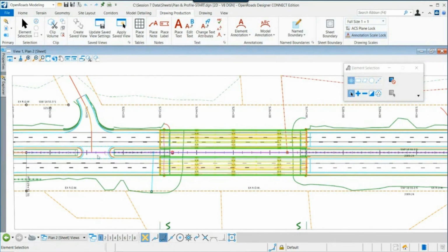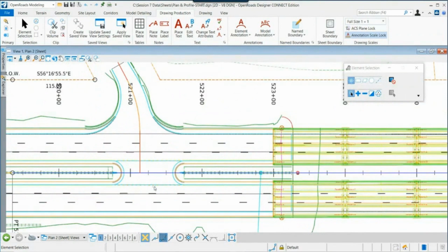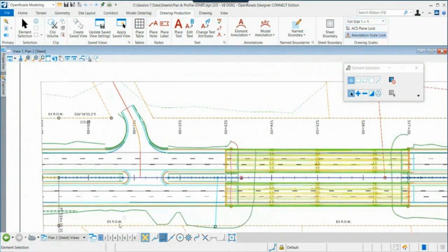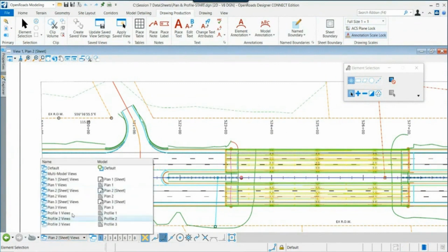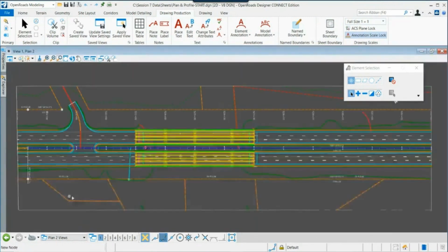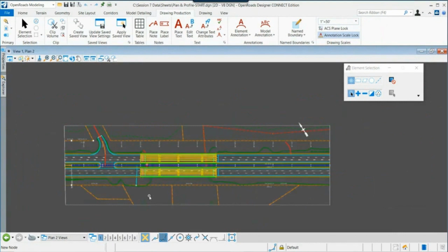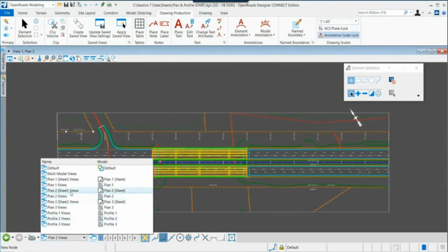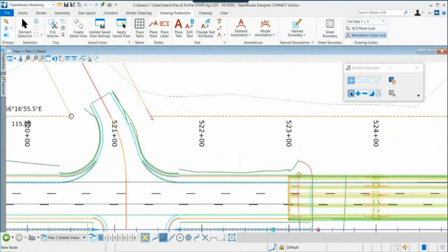Okay. Now, at this point, I could go a step farther, and this could be done at multiple places. I mean, I can come in here and I can make modifications. Do I want to make modifications in the sheet, however? I am in the sheet. Remember, I pointed out that there's going to be a sheet model created, which is what we're looking at now. But in addition to the sheet model, there's actually a sheet view created also, or a drawing model created for each view also. Okay, so here on this particular, if we wanted to make an annotation to sheet 2, let's say we're just going to put a call out real quick on these 2 points of right of way here at the intersection, and we wanted to annotate those with station and offset.